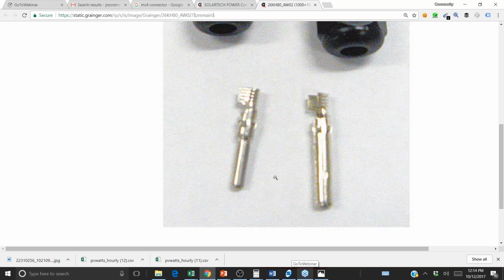What I want you to look at is this metal piece where it has kind of this half cylinder at the top, and that little half cylinder gets crimped around a copper wire. And where the failure point can occur is that where the metal copper gets crimped around this little point, that can slip if the crimped connection is not very good.